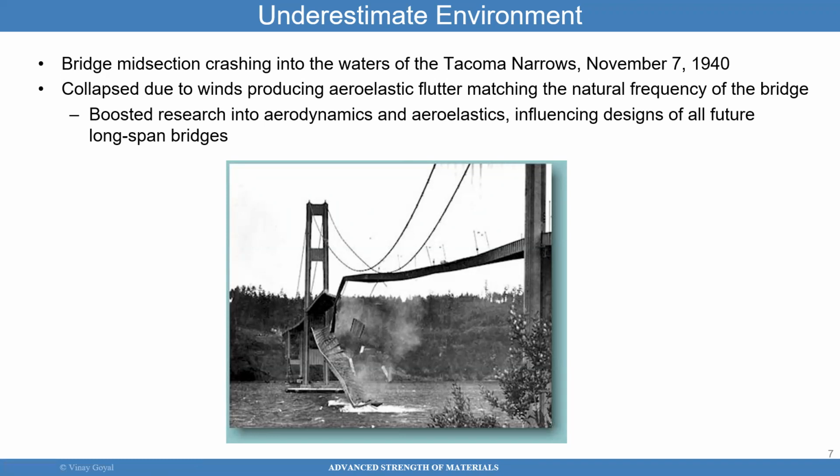If you type A380 flutter test, you will see an aircraft that was going to go through the certification process was put through a flutter test, and the A380 went through a dive to gain speed so that the forces, the wind speeds were such that flutter could be induced. And that's one of the tests that A380 or any aircraft has to survive. It's called the flutter test.